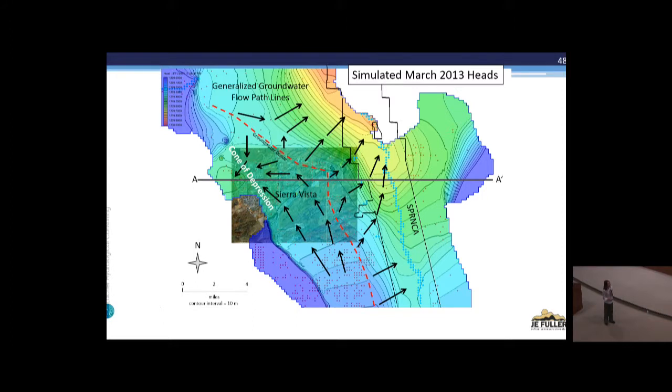Initially, there was no groundwater divide, but after some time, we've developed this groundwater divide that goes all the way down here. You can see the flow lines going off in different directions. I'm just putting a little point here as an observation point to look at what the heads are doing along this groundwater divide. It's a no-flow line. Water's not crossing.